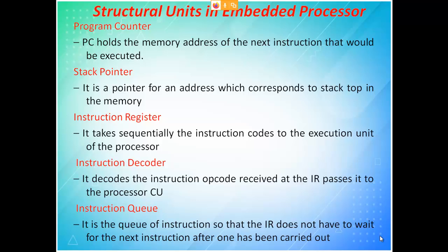Then automatically it goes to line number 8000. There finally after completing you will have an instruction called return. So when you see return, automatically it will go to the stack, take the content and place it in your program counter. So program counter, you are able to understand, will tell about the next line of execution.